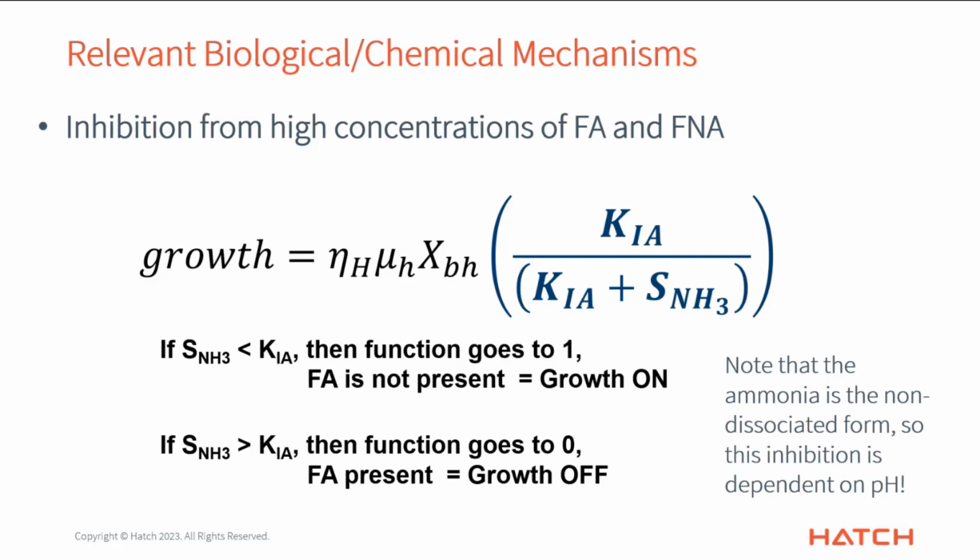It is this function, by the way, that allows people to make nitritation happen. If you want to do it with pH control, to take that first nitrification step, but not the second one, and end up with some nitrite, you can do that with some pH control if you're doing it at very high concentrations, say like right after it's been through a digester.